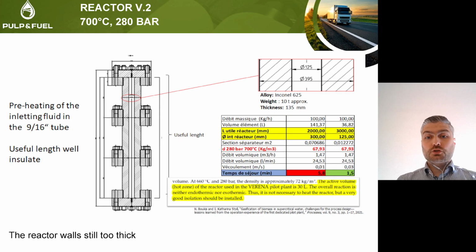Given for this project the high pH of black liquor, the high corrosive supercritical environment and the really critical temperature and pressure, the unique choice we had regarding the alloy was the Inconel 617. In order to respect the requirement of versatility for the residence time, a vertical reactor constituted by 3 modules which can be removed has been designed.